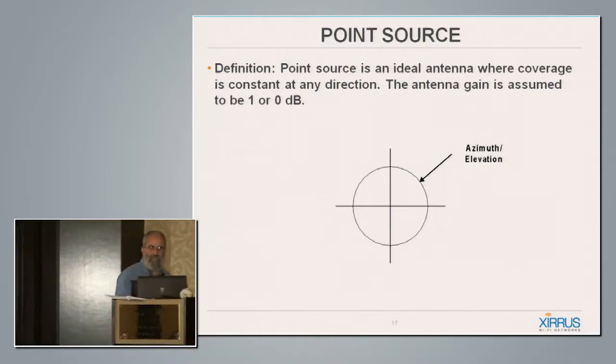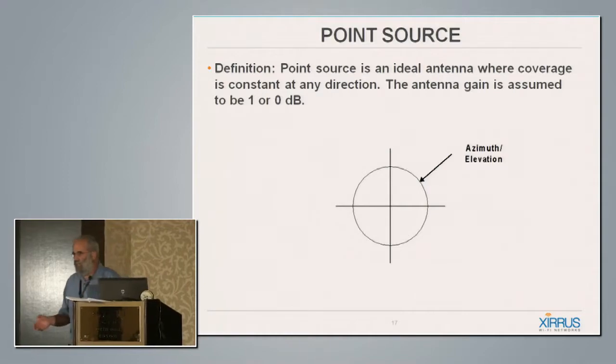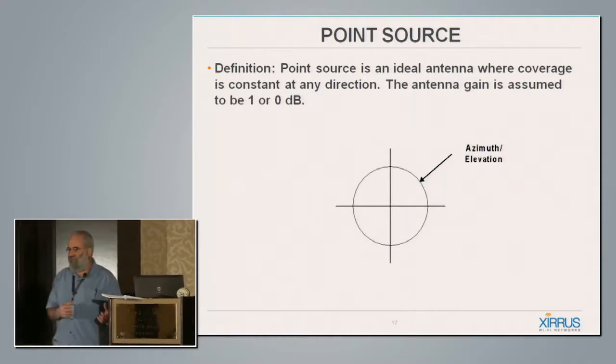So when we say the antenna has 20 dB, it's 20 dB relative to an isotropic source, and usually we say dBi to signify that it's isotropic. In some situations people would rather make it relative to a dipole, then it becomes dBd, or there are some other variations on that.